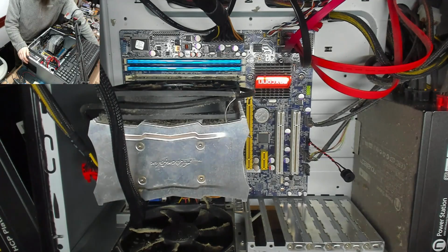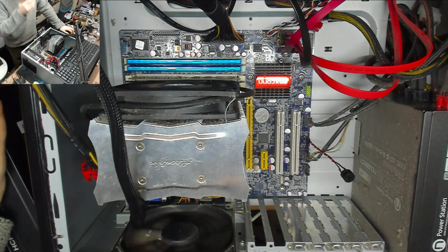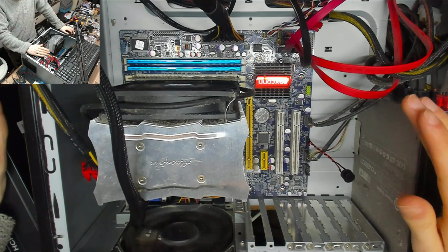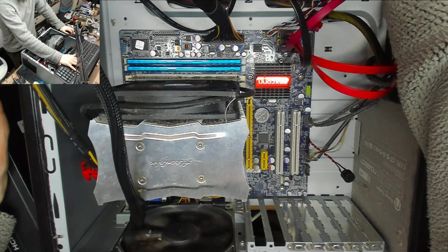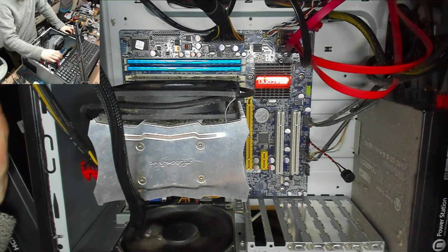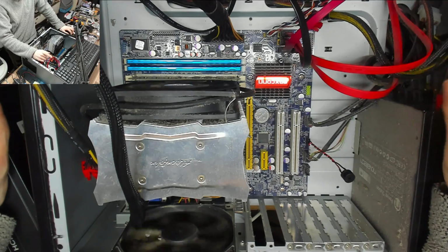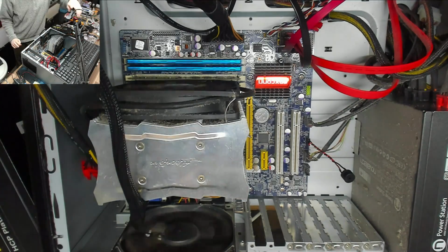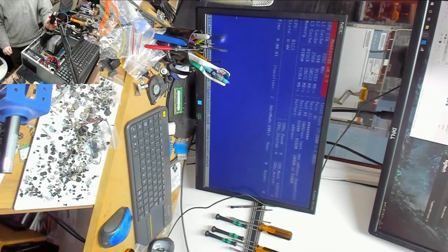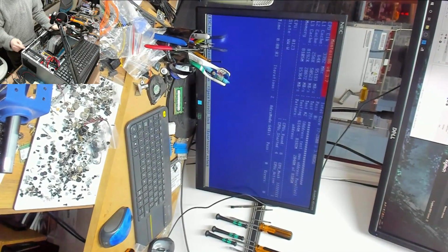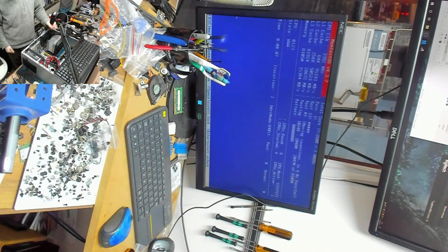Okay, right, powering up on the Antec power supply. So having the computer post this time doesn't necessarily mean anything. It's consistent posting I need. Right, and it has posted straight away. Now, because the drives aren't powered up, we should see it drop into mem test now, which it has done. So I'll just show you what's going on the screen. As aforementioned, we're on VGA output at the moment, so I'll just brutally turn my camera sideways. And as you can see, we're now running mem test.